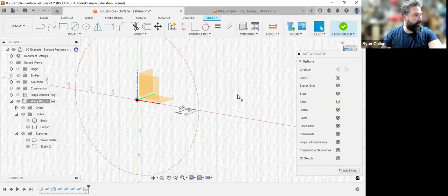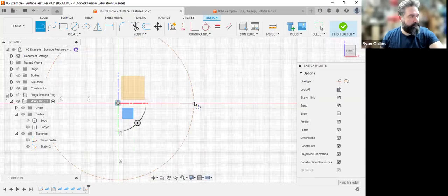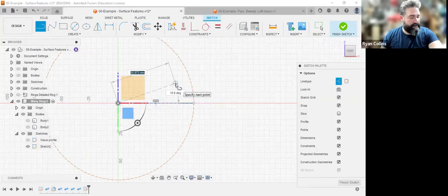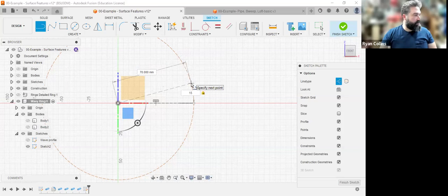So from the front, I'm going to make another reference point. So dot to dot, that's just one line. The reason I drew that is because I want to draw another construction line, but I want it to be up an amount. Sure, it's going to go to the edge, but I'm going to press tab. Let's kind of chop this up. Let's say 15 degrees. So I'm making increments, or if you want, 45.